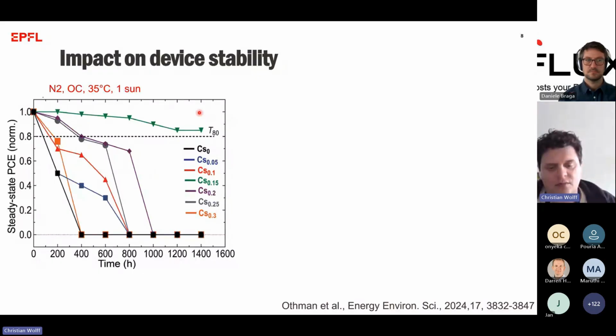And second, one thing that people often don't realize: if you have a module being installed in the field or on the roof, prototypically your installation is not going to be connected to the net straight away. What this means is that you have exactly the scenario I'm talking about. You are placing the cells and modules in the light under open circuit, and they are just sitting there for a little while. Exactly the scenario that I'm explaining here on the left side.